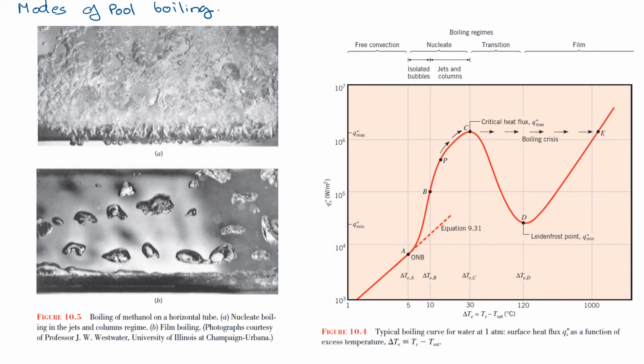Now let's look at an important concept in this chapter, which is pool boiling. Whenever you have water and you're boiling it on a burner or on a stove, your water is at rest. As you start applying heat to the water through a pan or through induction, say you're boiling it in a saucepan, your saucepan will start heating up, which will eventually create a convective current, or motion of that water, free convection.